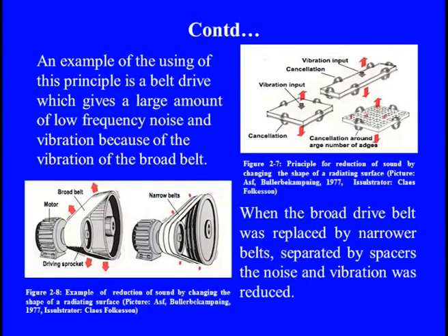So this is also one of the good techniques, and that is why in many passive control applications, perforated panels are used in place of solid panels. Or take another example, the belt drive. We know that when belt drives are moving, they create low frequency noise and vibration because of the broad belt. But when the broad belt drive is replaced by narrow belts, with spacers to separate them, we can straightway reduce that.